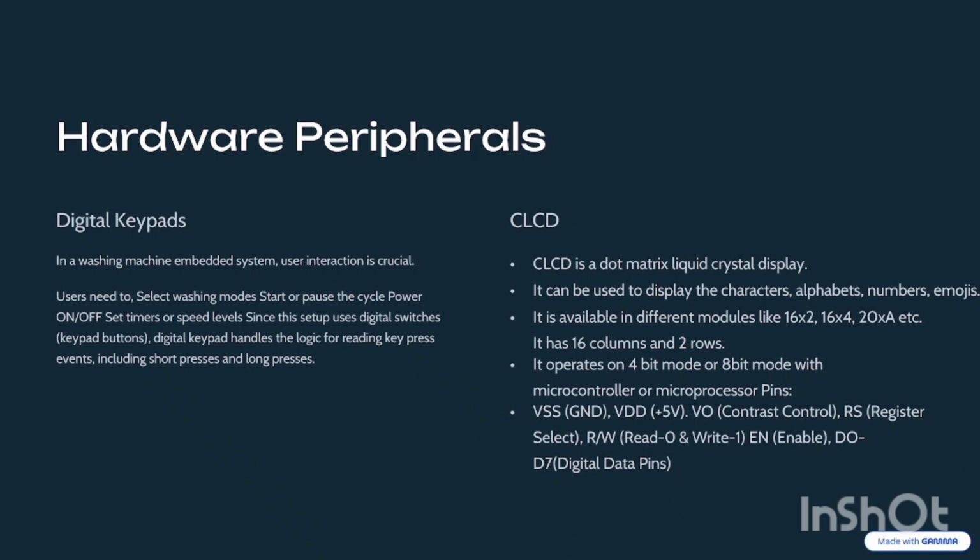And it has VSS, as we all know, it is a ground pin, and VDD, which supplies 5 volt, contrast control, register select, read or write. For read it is 0, for write it is 1. Enable pin, D0 to D7, which are digital data pins.